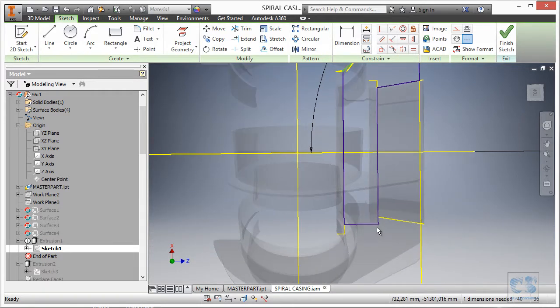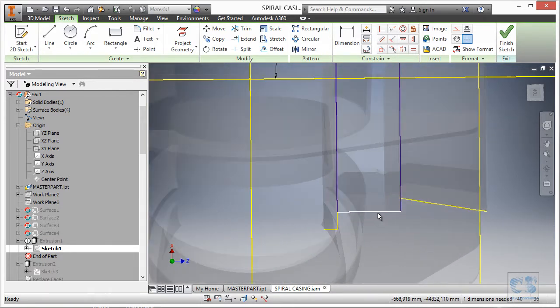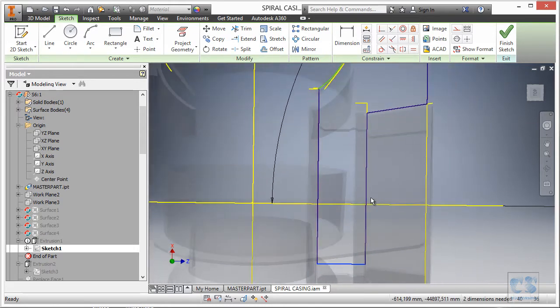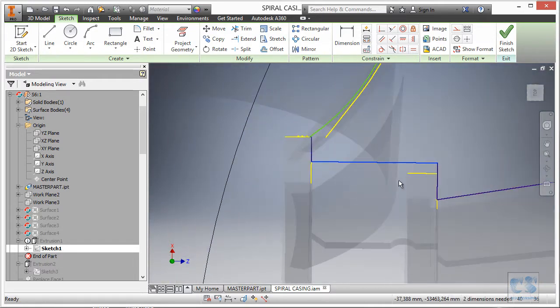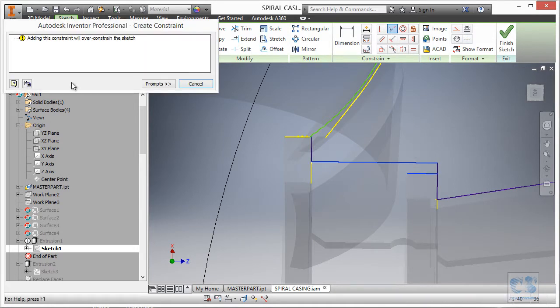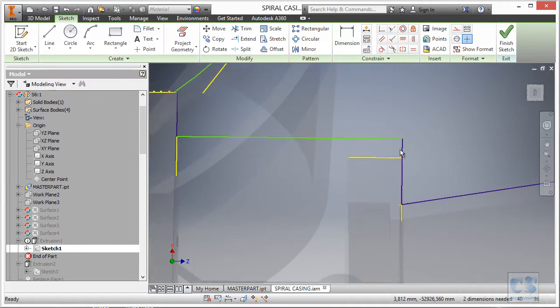And maybe you noticed, these lines moved when I deleted the pink vertical lines, and they are now attached on the wrong side of the reference geometry. So we just remove the constraint and reconnect them. Maybe we should just keep this like so, and let's try to reconnect this to this. So we have to remove all the constraints, or maybe look for which one is problematic.